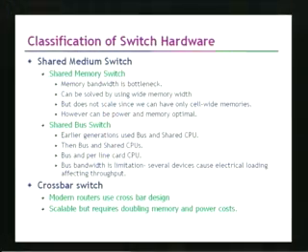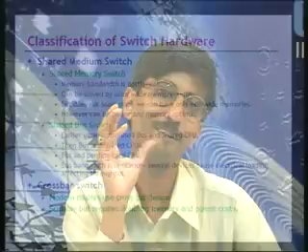However, this approach really doesn't scale, since we can have only cell-wide memories if the cell length is smaller. And as I already pointed out, it can be power and memory optimal. So shared memory switches are really good if the number of ports, that is n, is small. If the number of ports is small, then there is not so much stress on the memory bandwidth, that is manageable. At the same time, the advantage is that it can be both power and memory optimal.